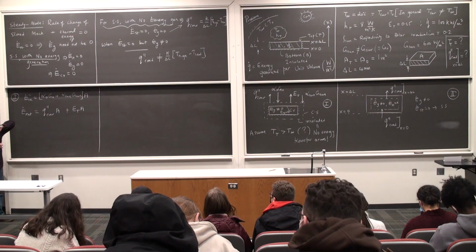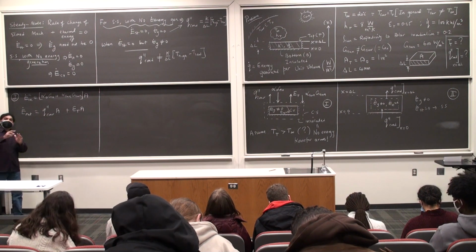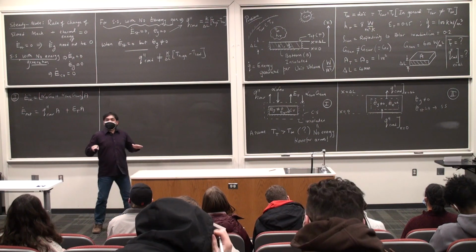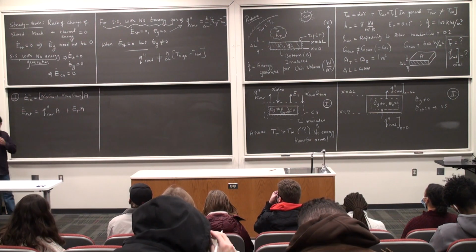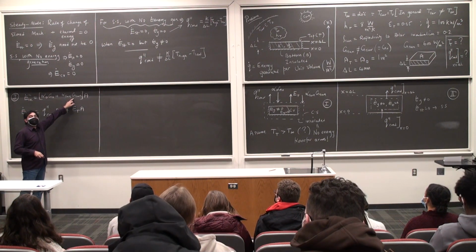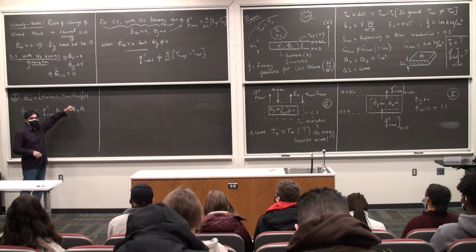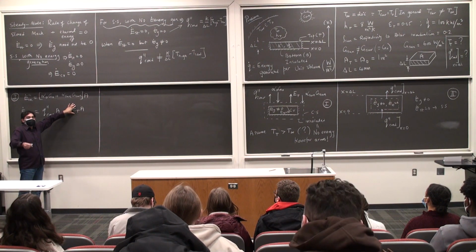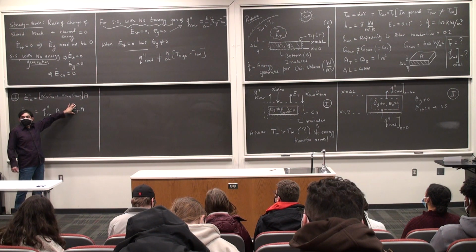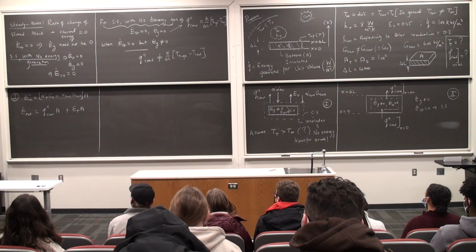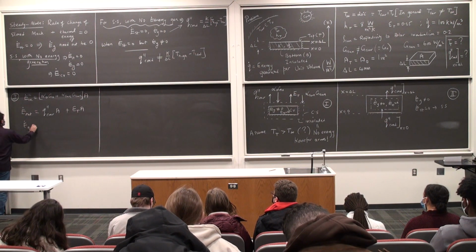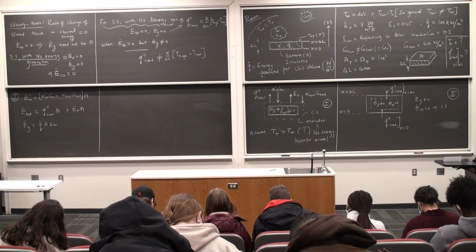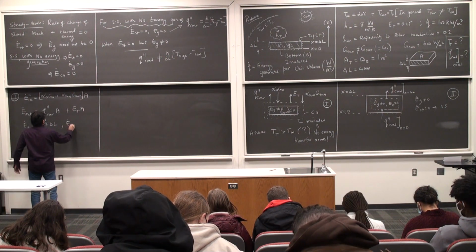Emission is completely different from the irradiation. Irradiation is a consequence of the surroundings. Emissivity is a consequence of the surface whose temperature you are trying to find out or whose temperature is known already. So they are mutually exclusive events. I can have one without the other. Most of the times, we will always have emission, because we are always looking at bodies greater than 0 Kelvin. E dot generated is q dot times A times delta L, E dot stored is 0.